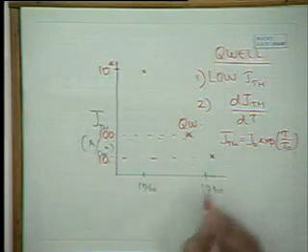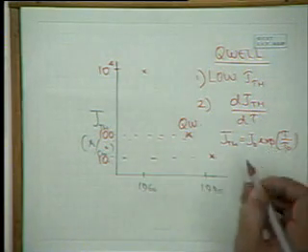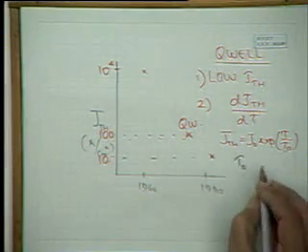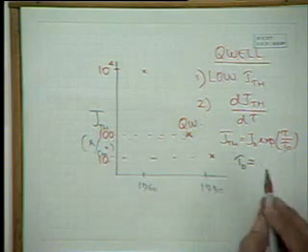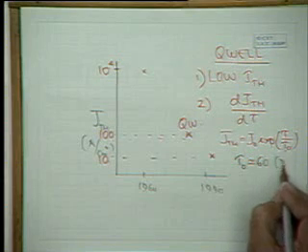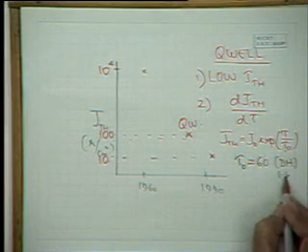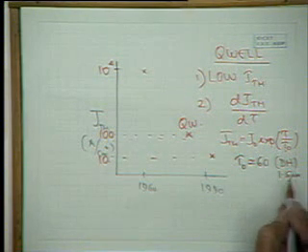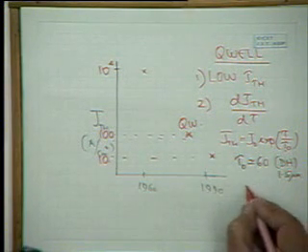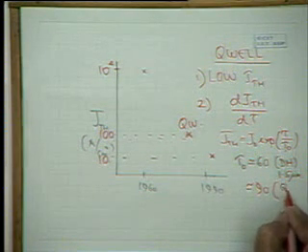So for a particular wavelength, if T0 is, say, 60 for double heterostructure lasers at 1.5 micron, T0 would be of the order of about 90 for a quantum well laser.